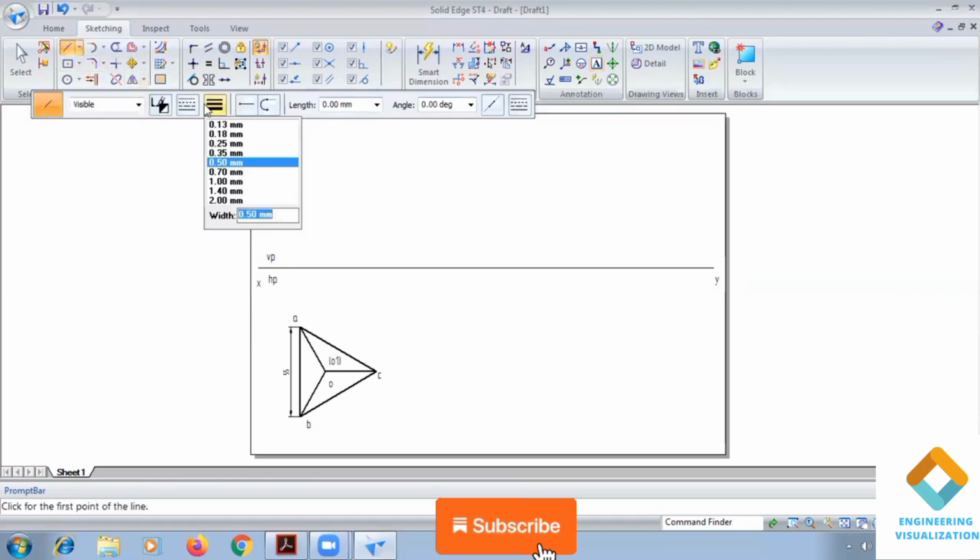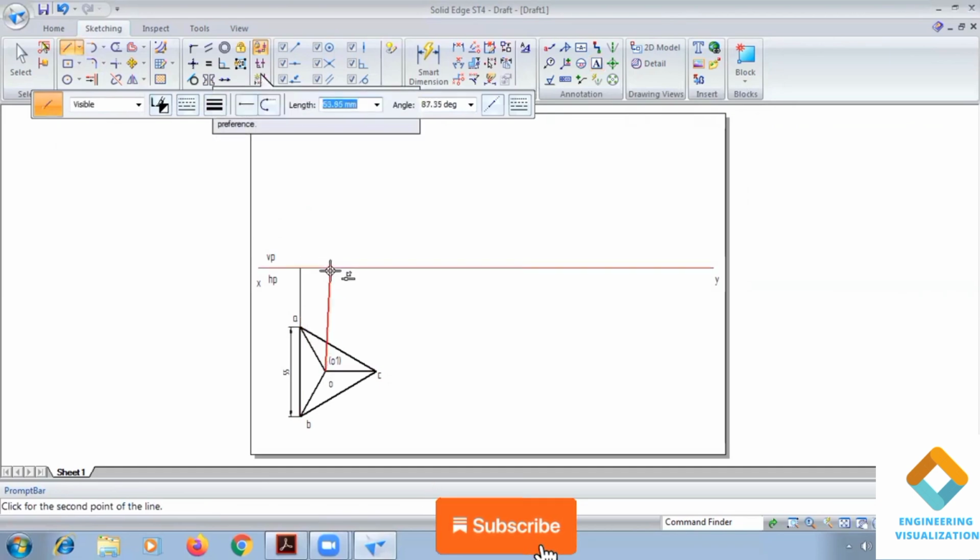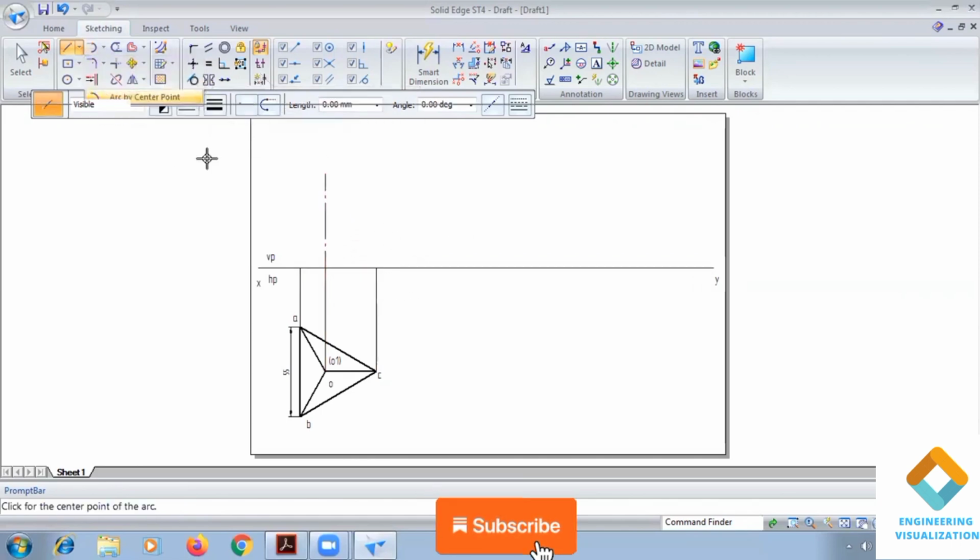Draw the projection lines upward. We don't know the axis length in this tetrahedron problem, so just draw randomly. From the one end which is parallel to x, you can see CO is parallel, so we cut the arc from this end with a radius of 55. Cut the arc. Now join it.